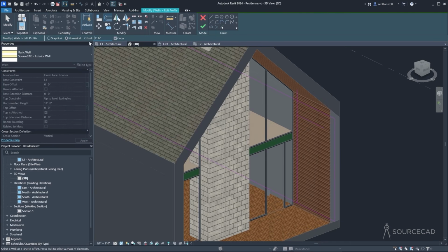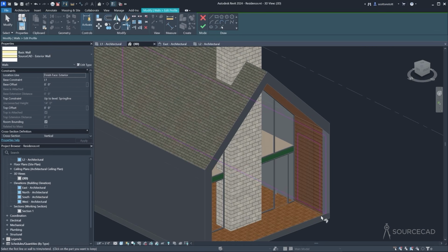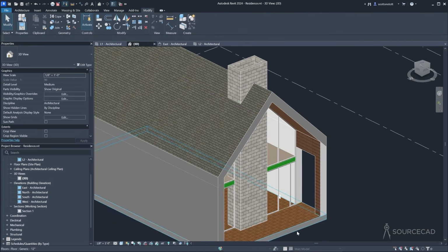That's the thickness of this wall, I remember. So I'm going to offset this line 1'6", and I can do that on either side just by moving the cursor and click on the left side to offset that like that. And then I can trim this together. And whenever you have a sketch like this, it has to be a closed boundary. This isn't going to work as it stands because we have kind of a boundary within a boundary. What we need to do here is use the split element tool to split this down below and then trim this together. So now we actually have a closed boundary. We'll accept that. And there you have a cutout.